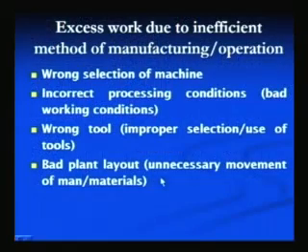The bad plant layout is about the setting of the different equipments and the machines in an organization. So, how these have been arranged and in which order these have been arranged, that plays a significant role. Improper plant layout design leads to the unnecessary movement of the man and material, which in turn increases the time required to complete the job. And if unnecessary movements are there, then that will increase the extra work required to do the same job. And therefore, the plant layout should be designed properly, so that the unnecessary movements of the man and material can be reduced.